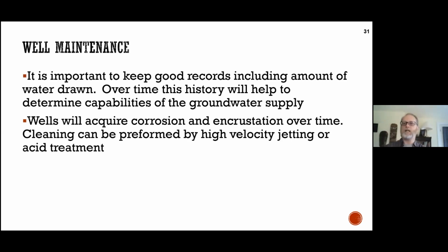The well screen may actually need to be blown out, so the pump is taken out, and you push water or air back through the screen to blow incrustations off with high velocity equipment, or actually with some chemicals to allow the particulates to be dissolved. And how you know that you need to do that is through the record keeping, right? The more records you have about what the pump is delivering into either a reservoir or directly into the water system, the better you can time any maintenance that you may need.